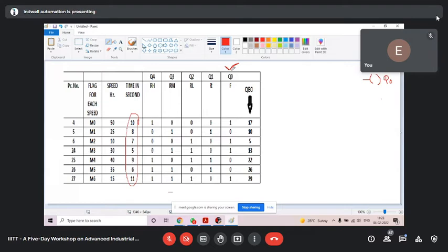Now you tell me, see this only. For Q0, you see here. It is started here. See, when Q0 is on, that time, which signal do we have? When we press start button, M0 comes, and immediately your motor should start in forward direction, correct? So as we press start button, M0 comes.